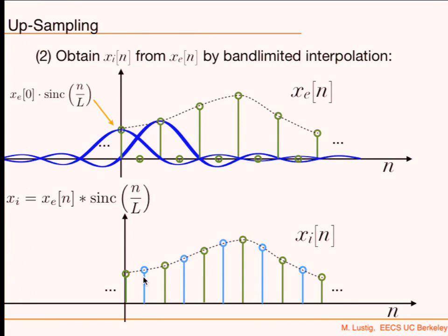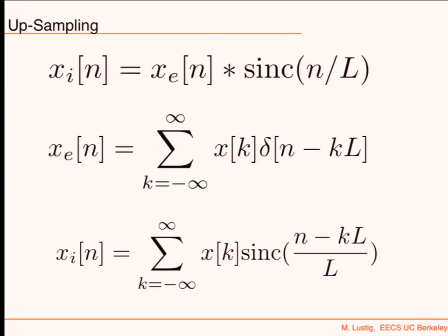If your original signal was not band limited and you got some aliasing, or maybe you got rid of some samples. But if we're considering band-limited signals, that there's no aliasing in the original signal, we want to resample it, and we consider, well, that was band-limited, then actually doing this is the best. This would work perfectly. But there might be a good reason to do linear interpolation. For example, if my original signal is actually piecewise linear. But that's something else, okay? Well, let's look at what's actually going to go. We're going to analyze that case too.